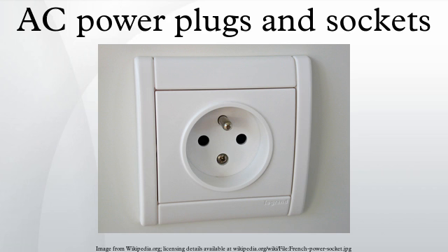Swiss SEV 1011. Switzerland has its own standard which is described in SEV 1011. This plug is similar to the Europlug, except that it has an offset earth pin and the pin shanks are not necessarily insulated, so plugs partially inserted into non-recessed sockets present a shock hazard. However, since January 1, 2013, only partially insulated plugs of type CE7/16 and of type J plugs are allowed to be imported and distributed to reduce the risk of electric shocks.